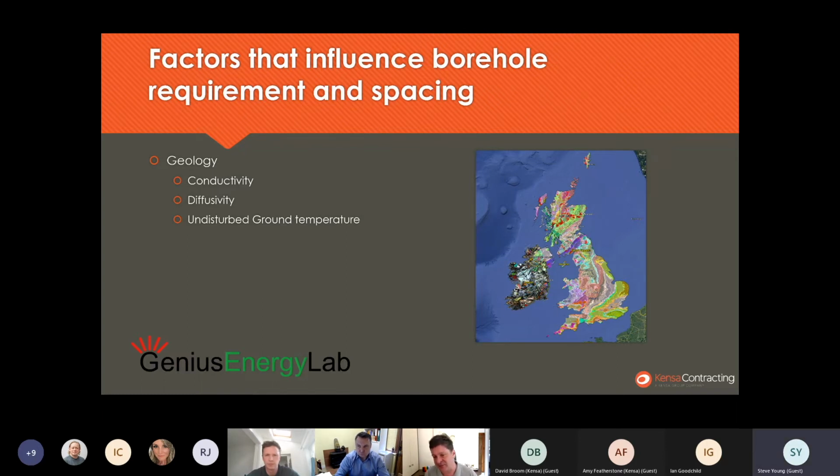Now, you might think from this that, out here in Norwich, it's just the green stuff, which is chalk, all the way down. Well, actually, you'll get through the chalk at some point and you'll be into either the greensand or Norwich crag, one or the other. So it's in layers. So just don't be fooled by a simple map like that. The strata is in layers and it can be very, very complex. Every type of geological condition that exists everywhere in the world, except two, exists in the British Isles.